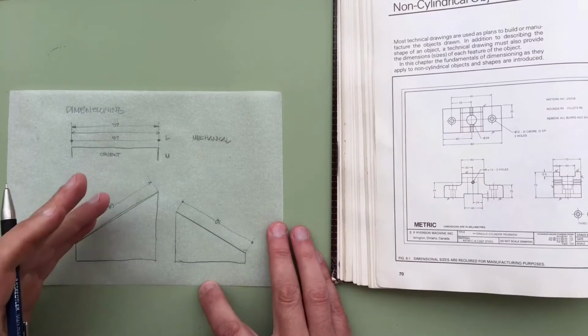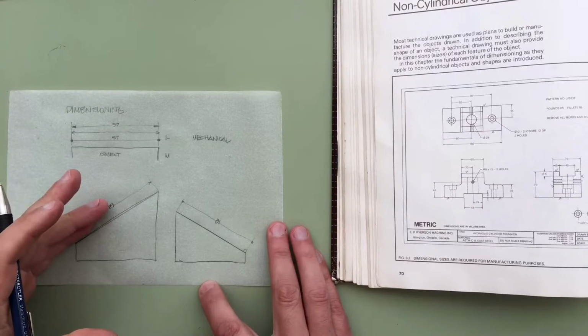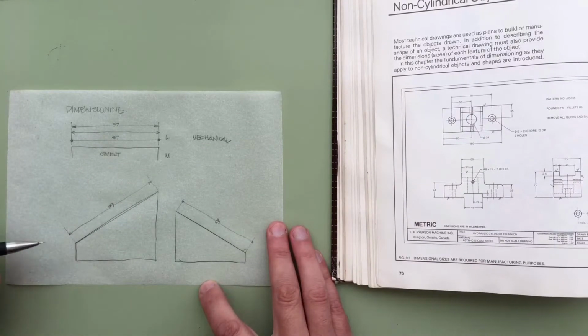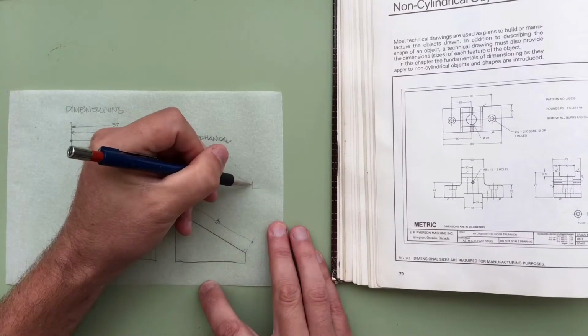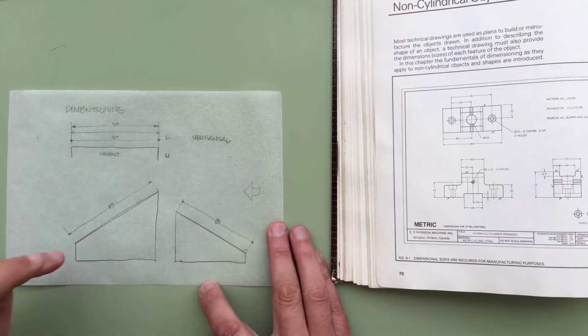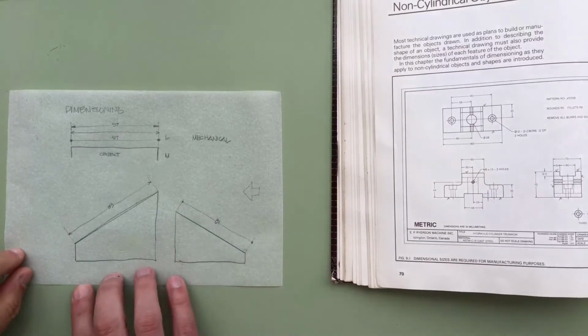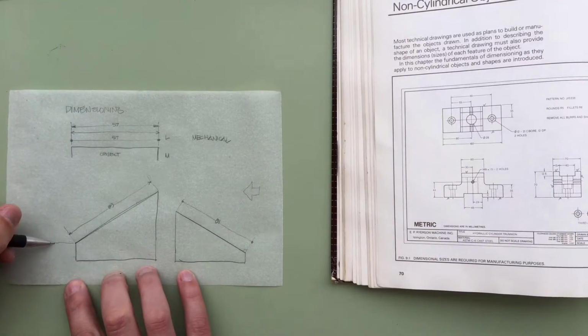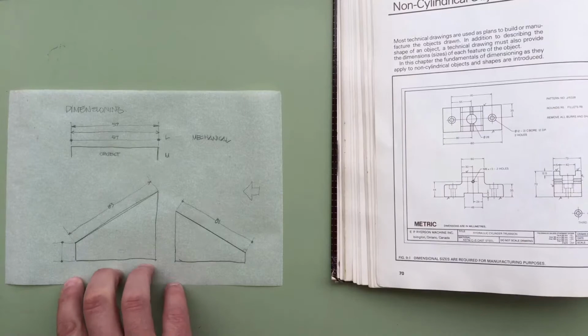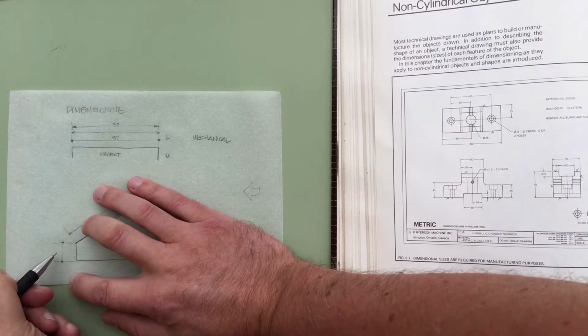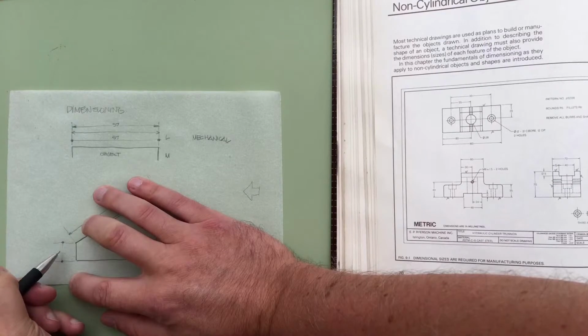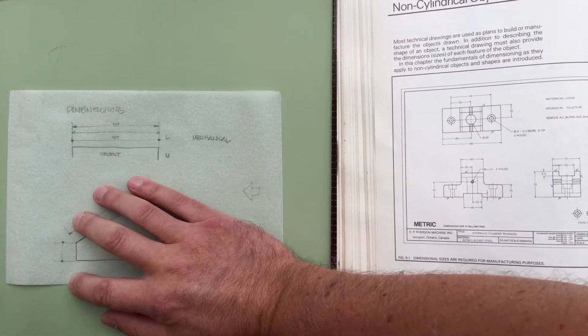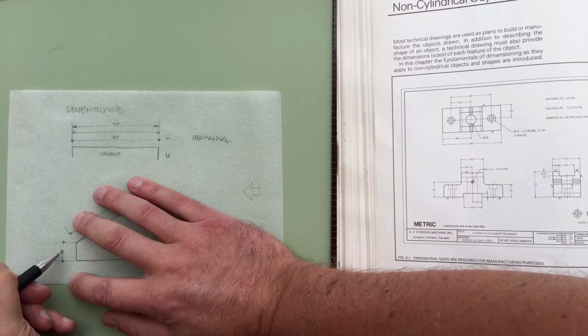Now, we never want our text to be upside down, and if we are dimensioning vertical edges, we make the text legible as read from the right-hand side of the page. So for doing these dimensions here, again, I'll run my witness lines out, dimension line up, put in my arrows, and then put my text in either immediately above the line or in line. Here I'll just draw this one in line to be consistent with the others.